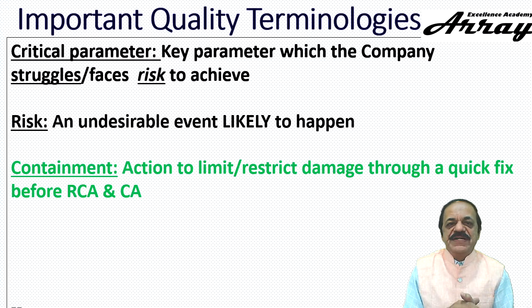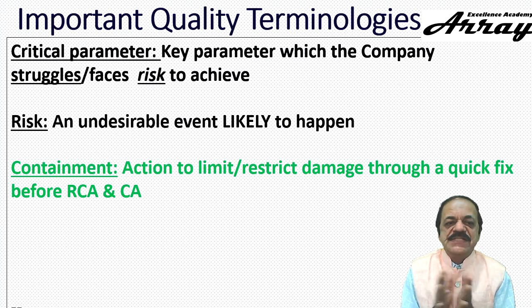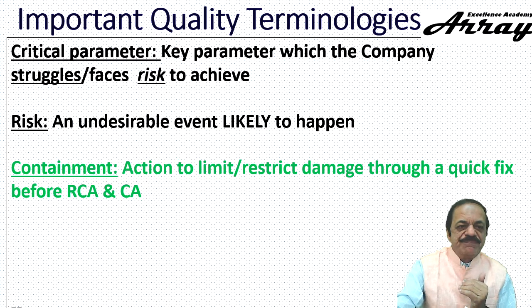Now what do you do with the defective item? You study them, you do the corrective actions for future, and at present you do defect repair. If it is repaired, re-inspect, and then again you will give it back to the production line to use in production. This is nothing but containment. Segregation of the bad lot, then further segregation of good and bad, handing over the good for production, repairing the bad ones, again checking, re-inspecting and handing over for production to ensure good products only reach the customer is damage control, which is called a containment.